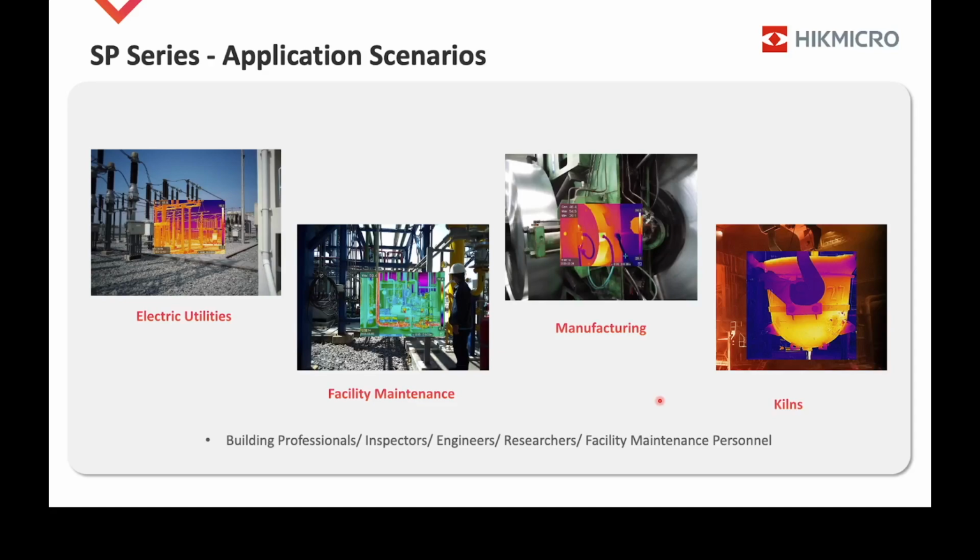The third one from the left is in manufacturing. Very often you find that bearings, when a bearing starts getting a problem, then it typically heats up, and with a thermal optic camera you can see what is happening with that bearing.